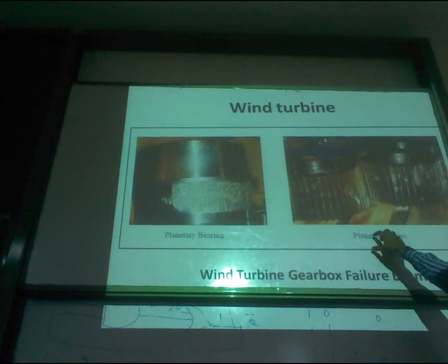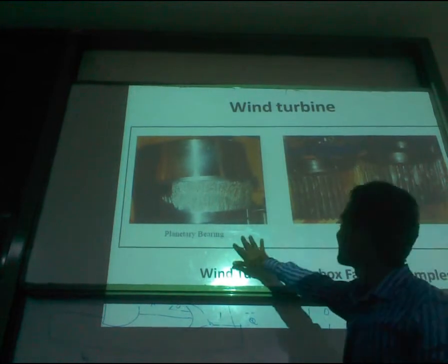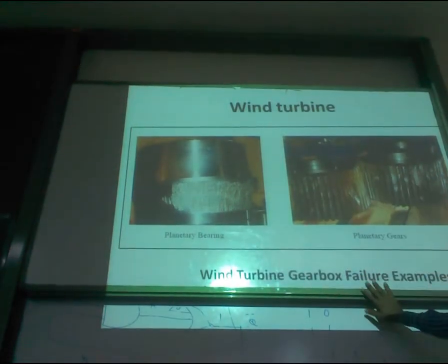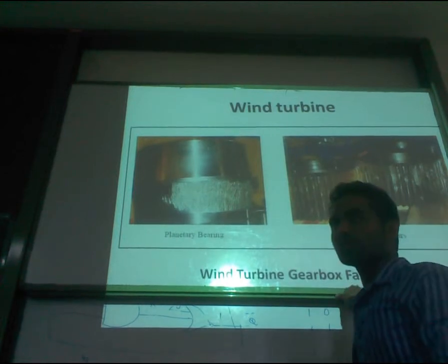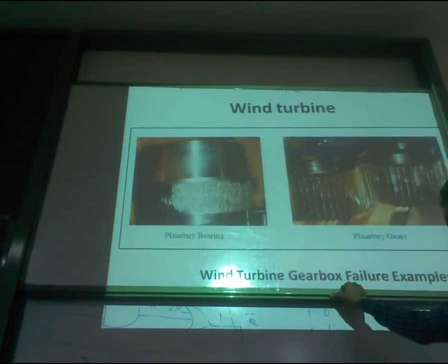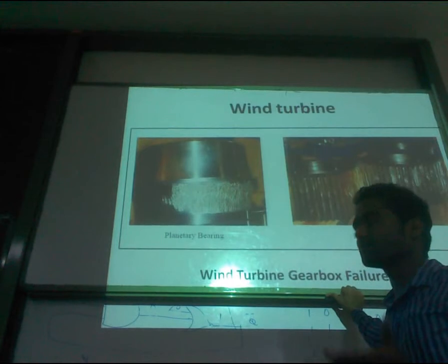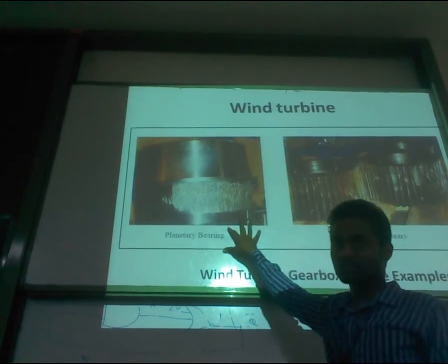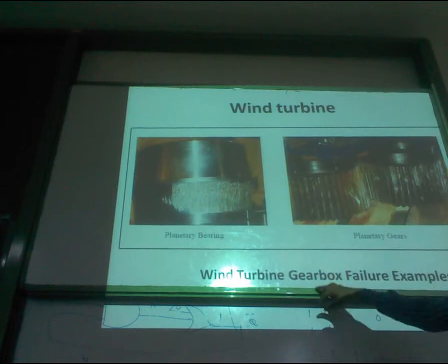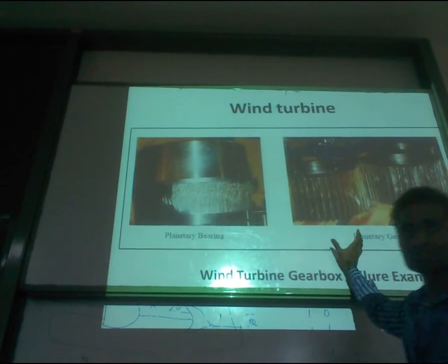To monitor the status of this bearing and gear, we can use the oil debris sensor inside the wind turbine also, because it detects the amount of debris, that is, the wear and tear taking place inside the gearbox of any engine.